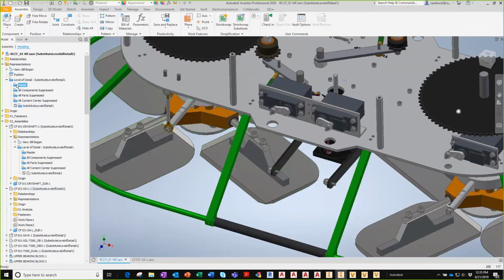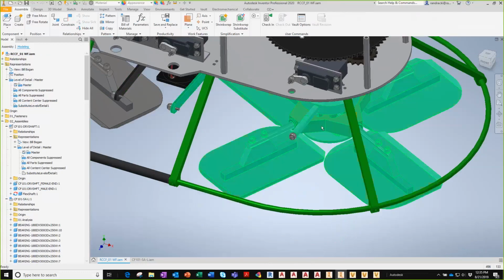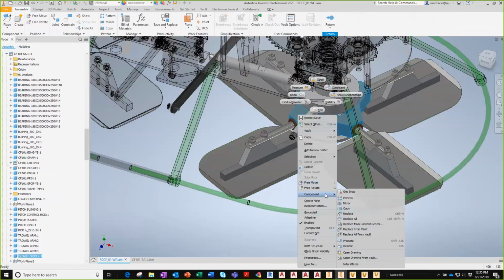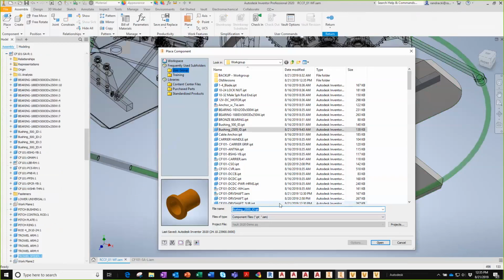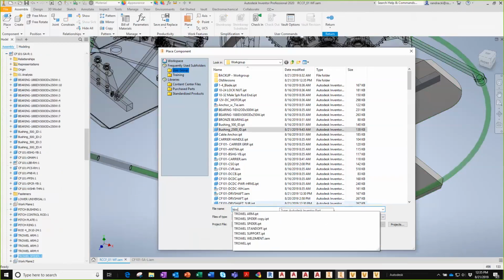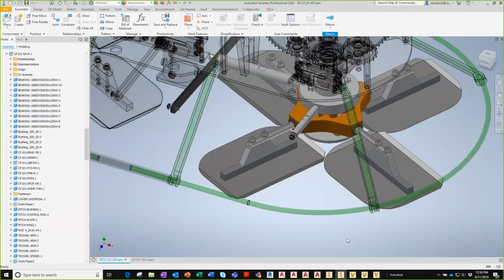All right. Now there's a time and place where you still might need to use the regular Inventor replace command, because I have a separate subassembly. But here I'm simply going to start typing. I want to find trowel. There's the copy that I would like. That is the one I want based on my preview. And we've got that all set.